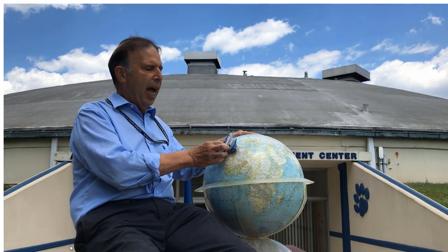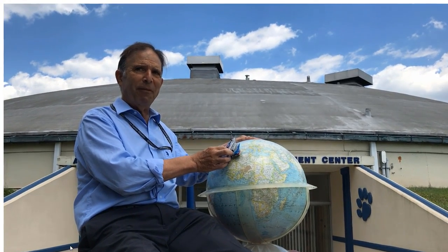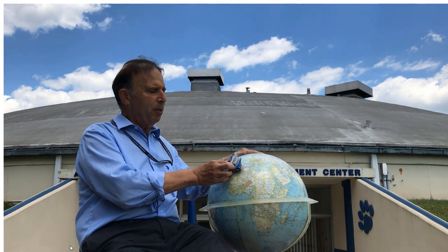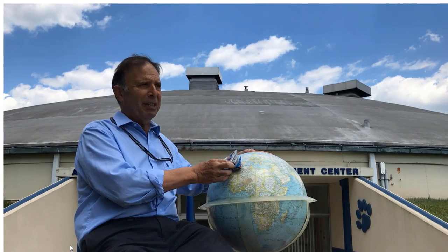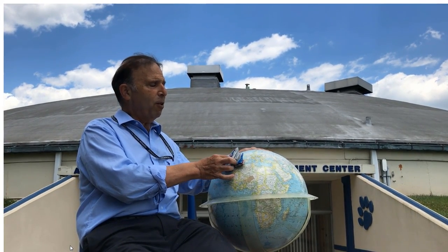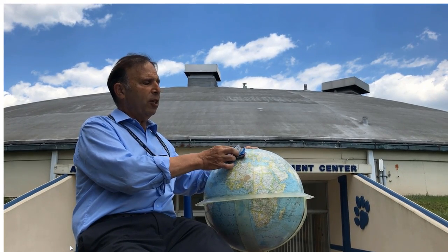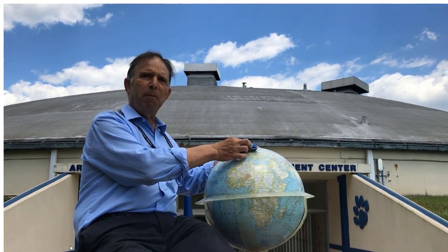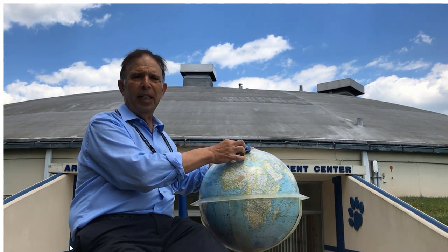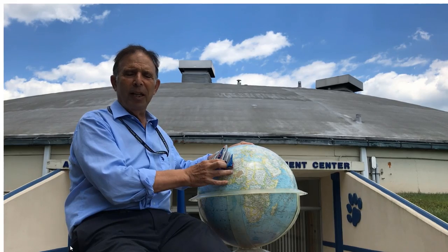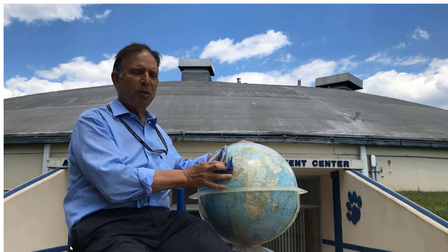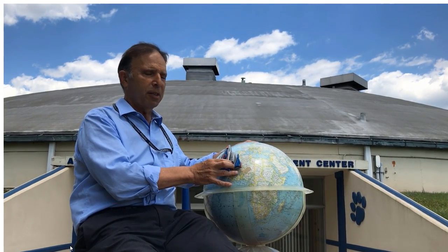The down component in the geographic coordinate frame of the transport rate, remember, is VE tan latitude divided by approximately the radius of the Earth. Of course, as we go close to the poles, that down component becomes infinite, which is why we eventually go to wander-azimuth coordinate systems or universal transverse Mercator coordinate systems.